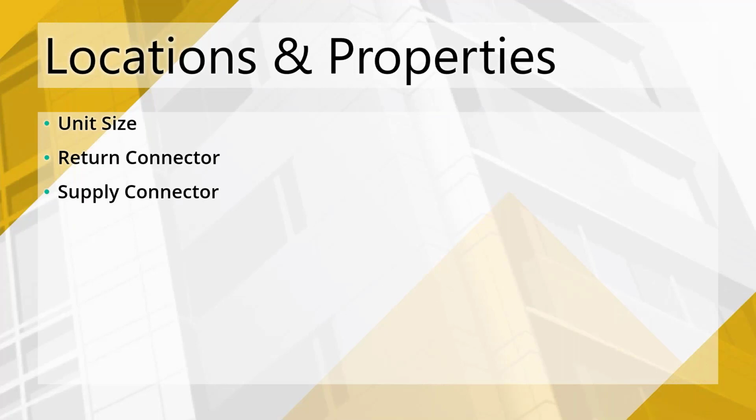And I am specifically going to be using the front, left, right, back, top, bottom orientation as specified in Revit, which means when I'm specifying the unit size, I may actually be using what you might consider odd values, but I'm going to do it on purpose because I want the unit to size correctly. I could always rehook things up if I really wanted to use the right named parameters, but I know in my head that all these units work pretty much the same way, so they're predictable. I'm going to leave this the way that it is.